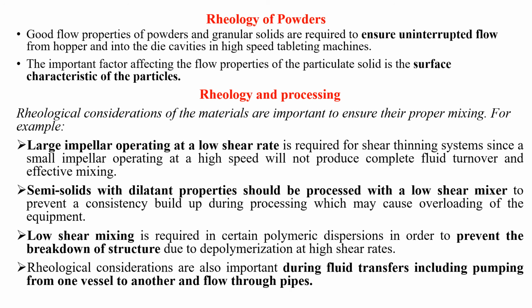Your polymer will no more be a polymer, it will be like dimers or monomers, and the physical structure or the nature of the polymer will be lost. It leads to depolymerization at high shear rates. So it is really very important to maintain low shear rates, and also during fluid transfers from one unit to another unit. These are the different areas in the pharmaceutical field where rheology plays a major role.